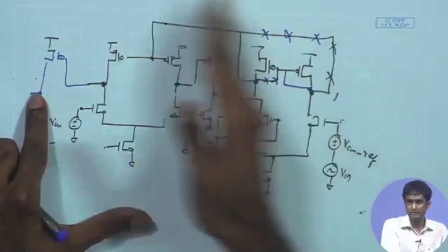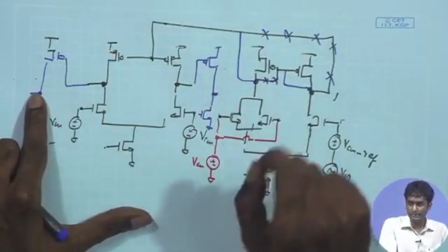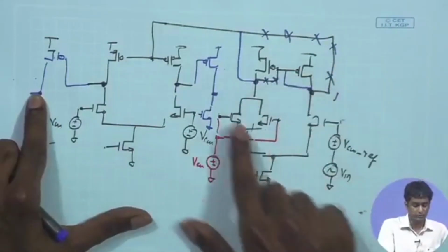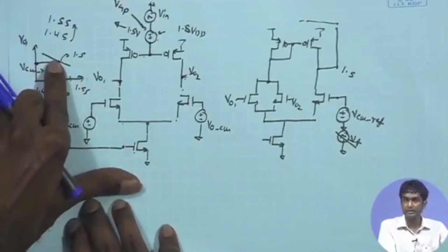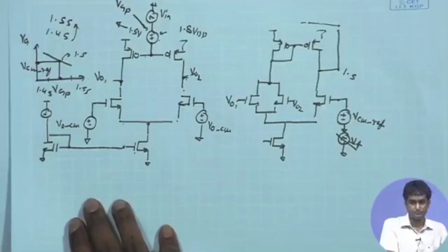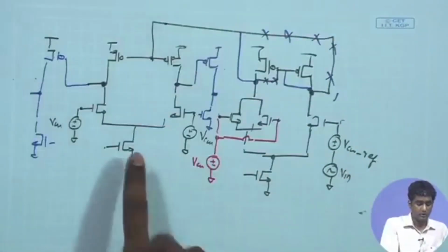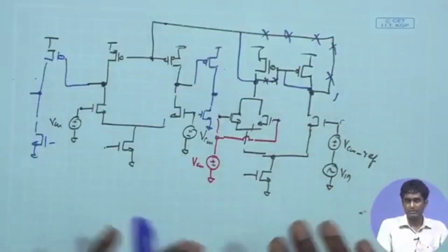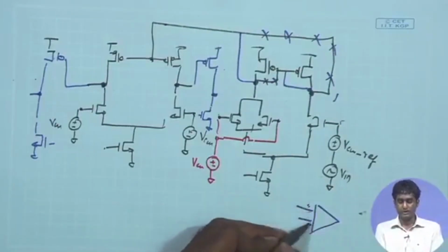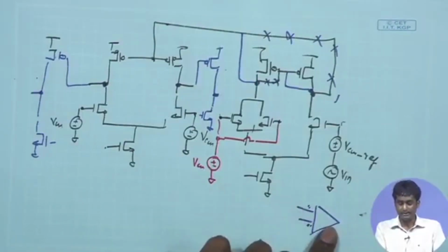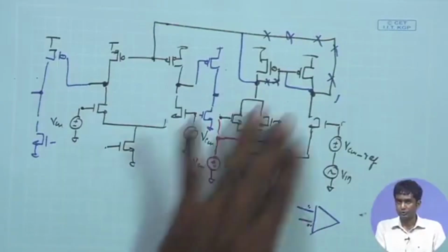When you open the loop, that negative feedback or stabilization effect is removed. Therefore, the required value over here to achieve the same voltage may be slightly different. So it may not be exactly the same, and for that you need to do this sweep in the open loop case, so that the output point comes close to the desired value. In the negative feedback, eventually it will not be exactly the same, it will have some error. Because remember in negative feedback, what do we assume? If there is an error amplifier, we assume that once you connect it in negative feedback, these two inputs are exactly the same. But that does not happen, because with a finite gain amplifier there will be some minute difference between these two inputs, and that is ensured by the negative feedback.